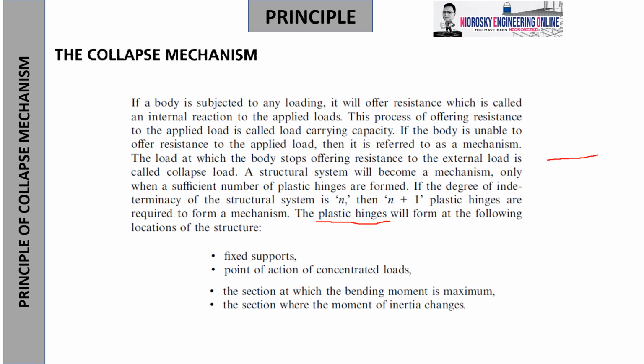So, therefore, in this illustration that we're going to draw, if you are to achieve, let's say, plastic deformation through deflection, then ang plastic hinge dito ay yung nagtupi dito. Ayan. That will create the plastic moment. Let's call it M sub P. And here is the plastic hinge. Let's say theta sub P.